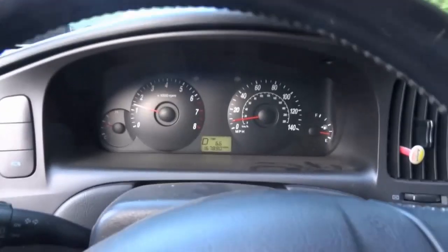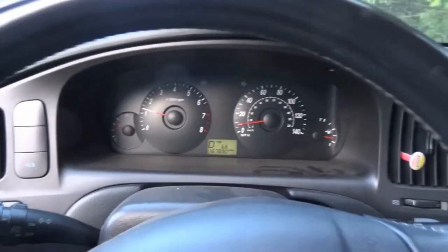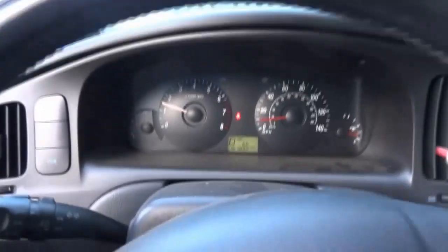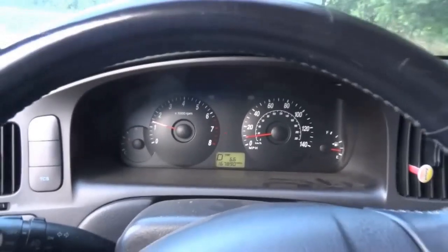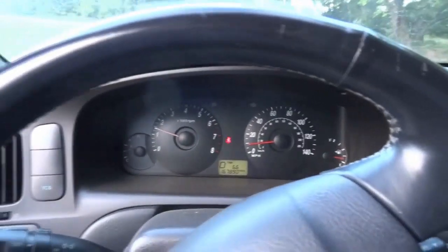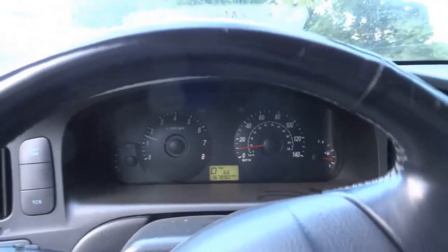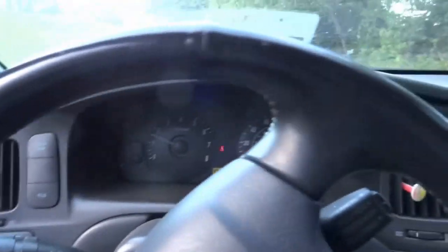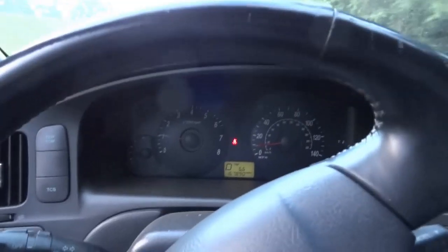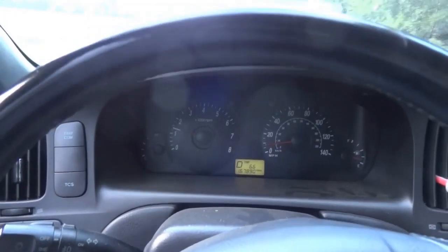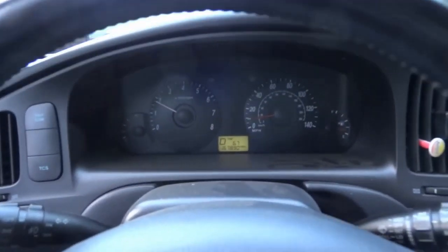I don't know if it's a leak on the intake, but it sounds like a leaking turbo. It's like when you have a leak on the inlet side of the turbo, you know, on turbocharged engines, when you have one of the seals or maybe a clamp between the turbo and the intercooler, if you have a leak like that, that's kind of the sound it's making. Listen.